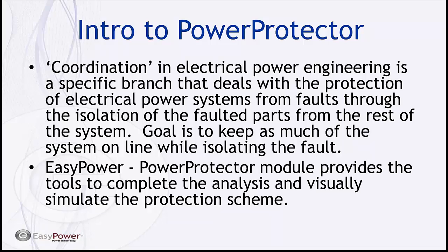Before these types of tools were available, engineers had to take performance curves or TCC curves in either onion skin or mylar and overlay them to see how they would basically trip based upon the short circuit calculations of the circuit, and then come up with other techniques of making adjustments to make sure that you had some sort of coordination between series protective devices.